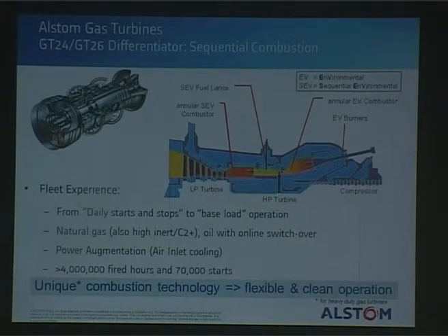It gives the reason why we have it. First, you get more power for the same size of engine. Secondly, it's very flexible because the second combustor you can just switch it off. Also, because this is an auto-ignition process, the combustion is much easier to control.